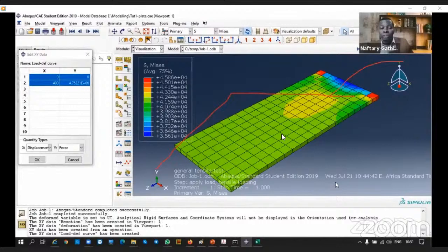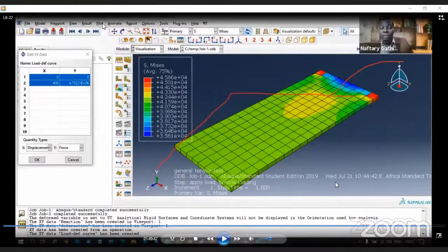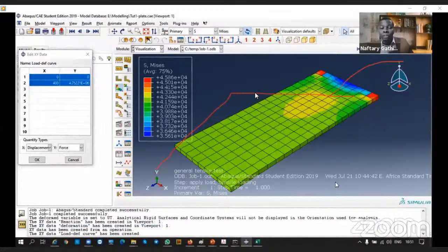No, you just need to go to the mesh model. You just go to your meshing. You just go back to, in your model, you go to where you generated the mesh, and then you can adjust the size of the element. So yes, you can specify the size, you can even specify the number of nodes that you require. You don't have to go back and change the size of your model. What you need to change is the size of your mesh.